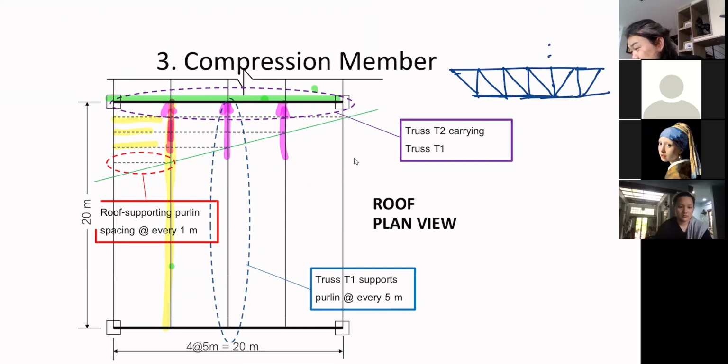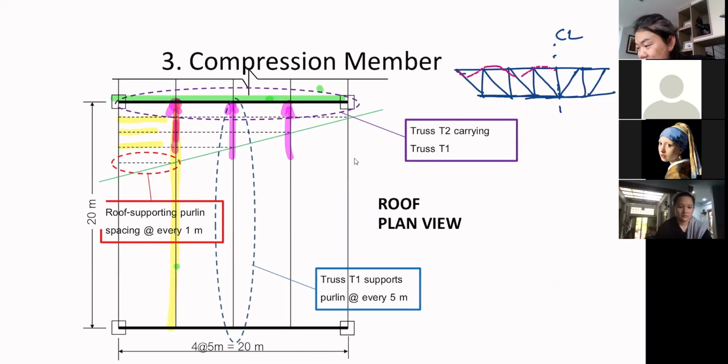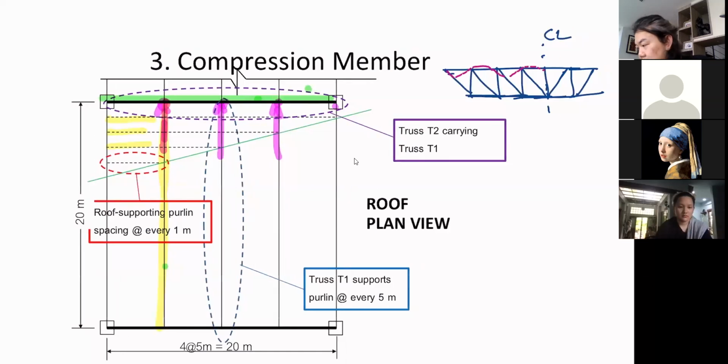Let's say this is the center line. You see that for the up and down direction, the top chord member can buckle like this, right? But for the in and out of this plane of the iPad, this purple point is where it is going to serve as the bracing, which is perhaps at this location, that location, then that location.